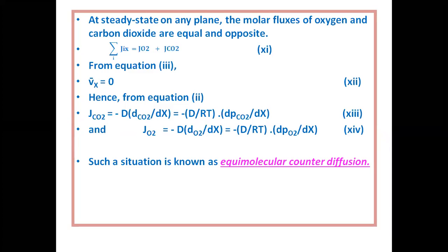Once we're discussing the reverse reaction, the CO2 may decompose to C plus oxygen. In blast processes, CO2 is not very stable, but a good amount of carbon is there, so CO2 sometimes reacts with carbon to give CO. Sometimes that CO is also not stable, and through diffusion, the carbon monoxide dissociates to carbon dioxide and free carbon. That free carbon is sometimes deposited in the iron lattice, so an excess amount of carbon is found.